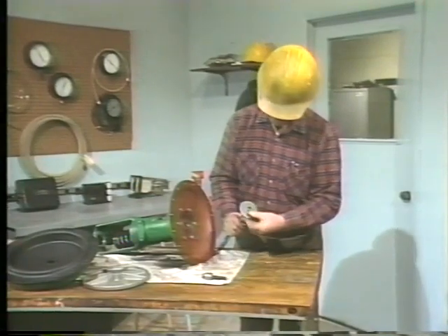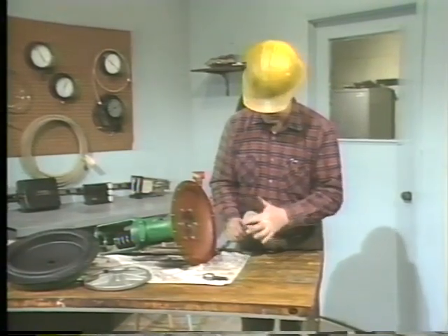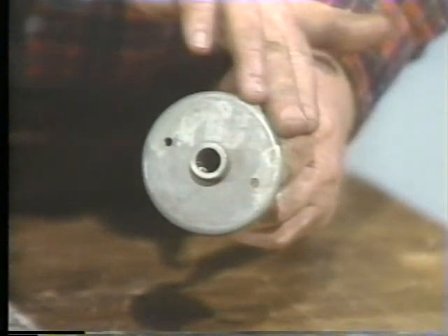The lower diaphragm plate also provides solid support for the flexible diaphragm. In addition, the plate forces the diaphragm against the upper plate, squeezing it so that it forms an airtight seal around the actuator stem that prevents air from leaking from the lower diaphragm casing into the upper casing. The lower plate should also be free of any rough spots that could damage the diaphragm.